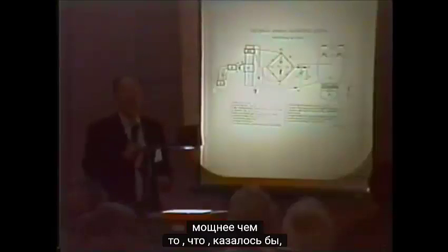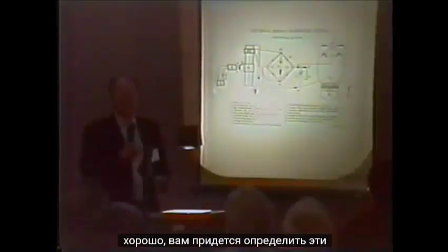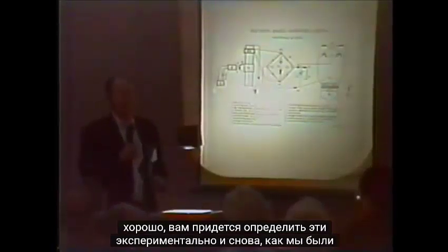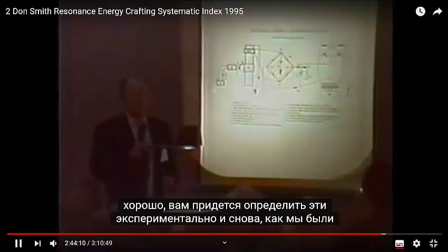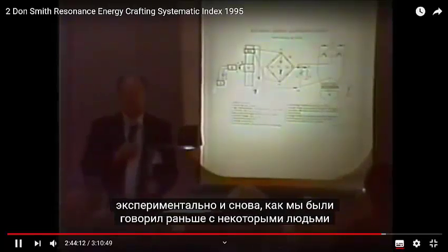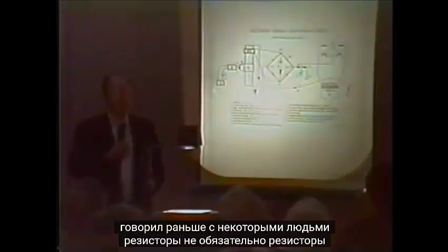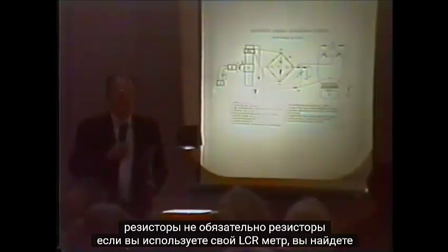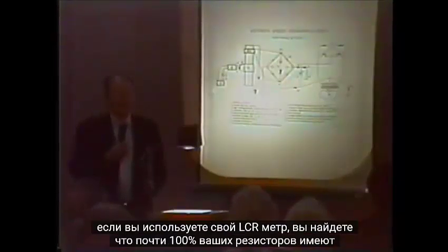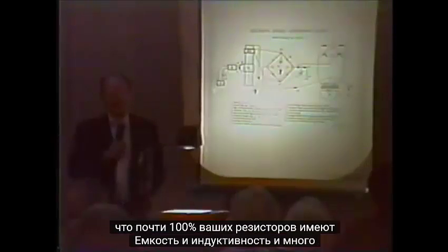What size resistors do you use for a voltage divider? Okay, you'll have to determine those experimentally, and again, as we were talking earlier with some of the people, resistors are not necessarily resistors. If you use your LCR meter, you'll find that almost 100% of your resistors have capacitance and inductance.